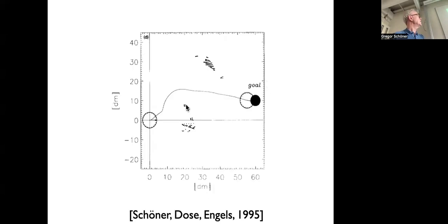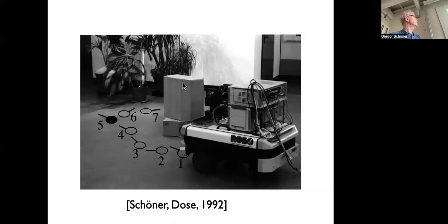So for instance, here, this is the kind of measurements we had. These little dots are measurements where the system detects obstacles. This was based on detecting everything that is not in the plane. You're comparing the image that you predict from the two cameras, if everything was in the plane, to the actual images, and everything that's not in the plane is an obstacle, because it arises from the plane. Then this was a case where we found this unique path to the target, and I do believe these boxes here are the obstacles, and there's some arbitrary place here defined as a target.